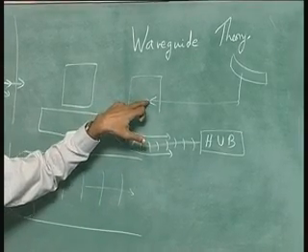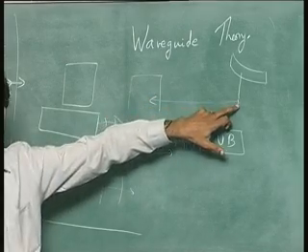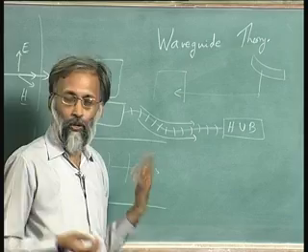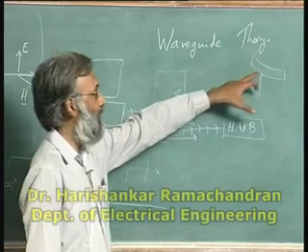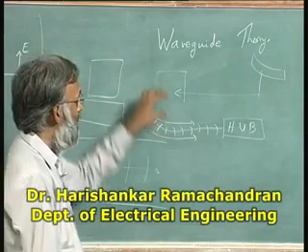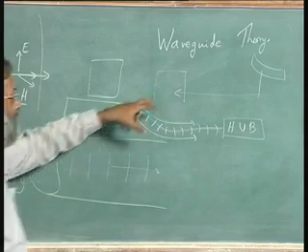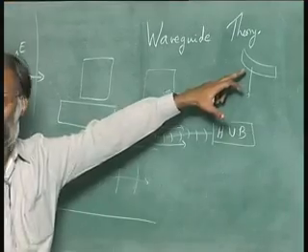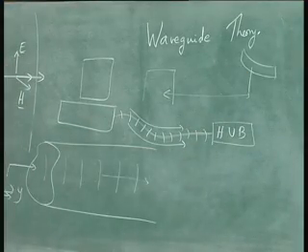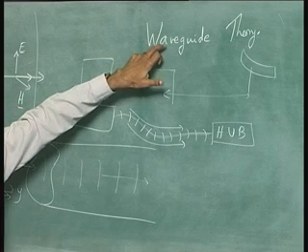So, this high frequency signal has to be taken there, and it is maybe 10 kilowatts of power that must be given to this antenna. It has to go through a pipe, and such waves that go through pipes and drive a radar antenna, these are waveguides.